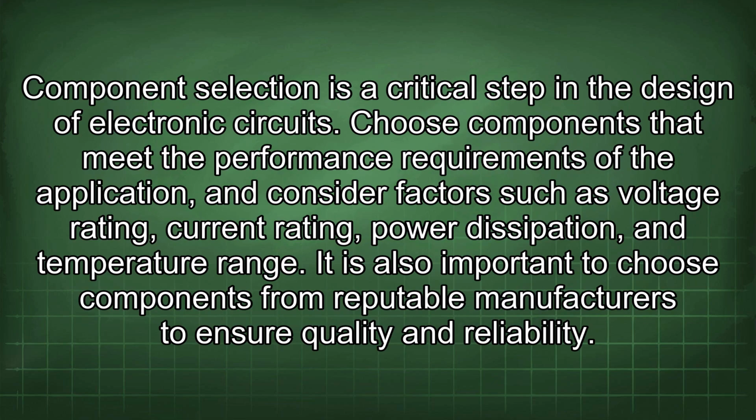Component selection is a critical step in the design of electronic circuits. Choose components that meet the performance requirements of the application and consider factors such as voltage rating, current rating, power dissipation, and temperature range. It is also important to choose components from reputable manufacturers to ensure quality and reliability.